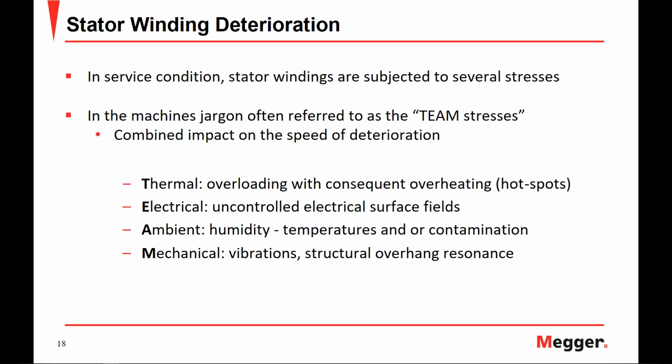As an example of these TEAM stresses, one could be overloading with consequent overheating or hot spots as a thermal example, uncontrolled electrical surges as your electrical stress, humidity and temperature or contamination as your ambient stresses, and vibrations or structural overhang resonances as your mechanical stresses.